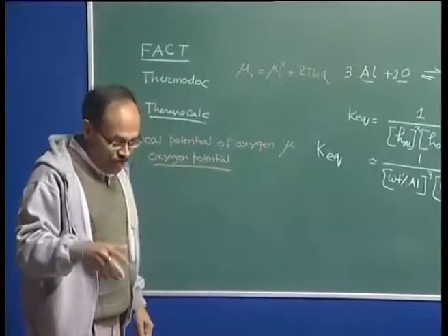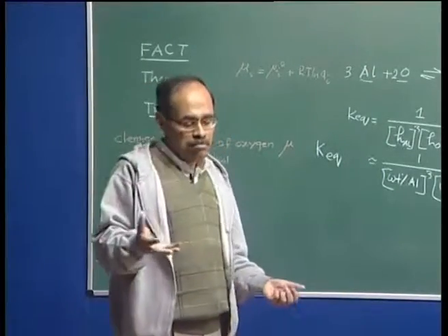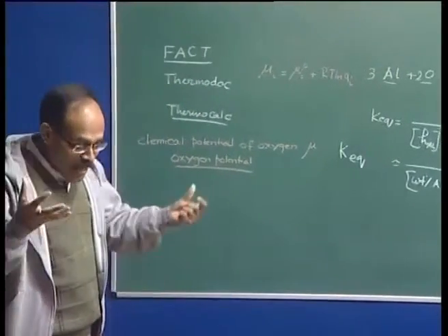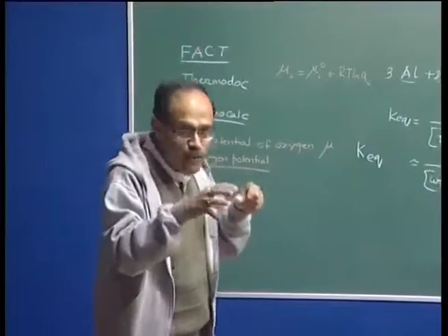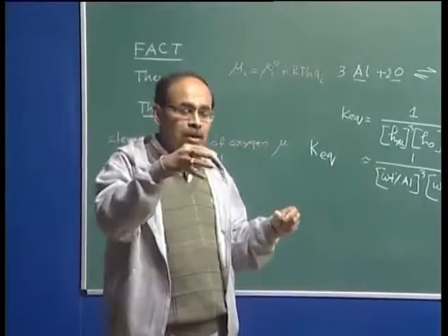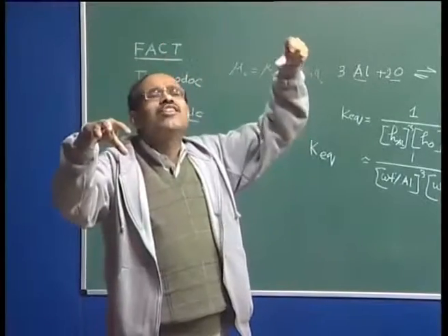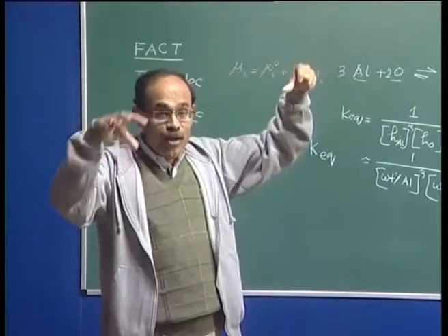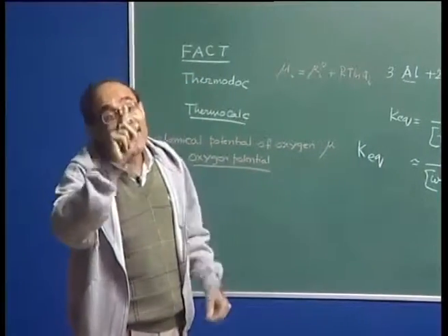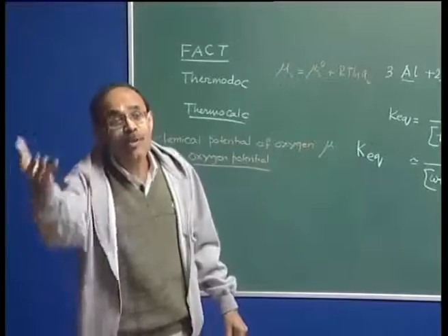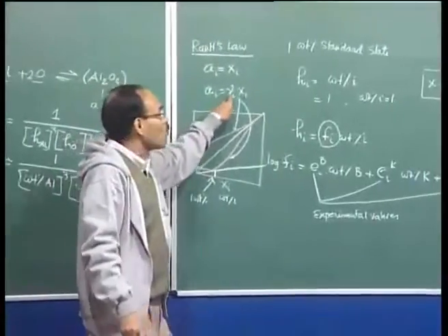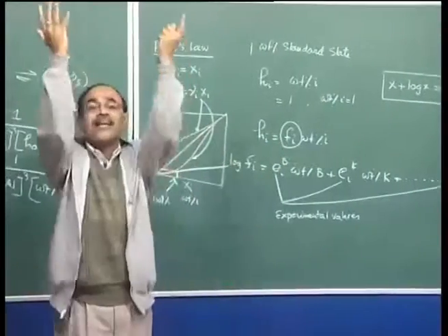We must understand that when we studied this famous Darken's couple, we saw that in terms of concentration, it is possible to transfer carbon from a region of lower concentration to a region of higher concentration, because in the lower concentration region the activity of carbon is much more, owing to the presence of many other solute elements which influence it through the activity coefficients and enhance the activity of carbon.